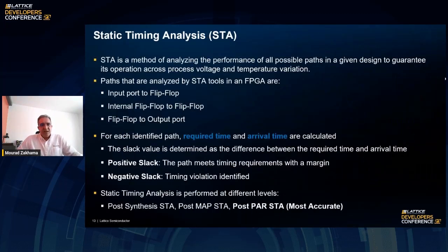So what is STA, static timing analysis? STA is a method of analyzing the performance of all possible paths in a given design, and making sure that we can guarantee the operation of these devices across process, voltage, and temperature variation.